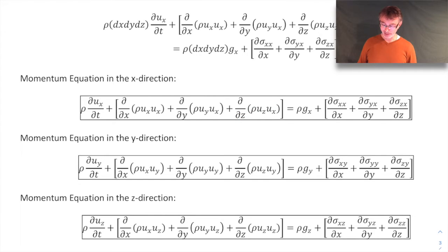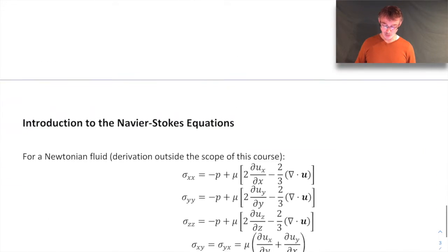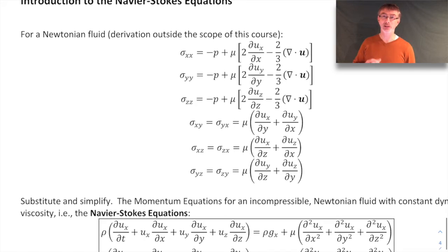But like I said, it'd be nice to be able to express the stresses in terms of velocities, just like what we do for a Newtonian fluid. So that's our next step. We're going to use what's known as a constitutive relation. A constitutive relation just relates various quantities together. Like the ideal gas law is a constitutive relation because it relates pressure, density, and temperature.